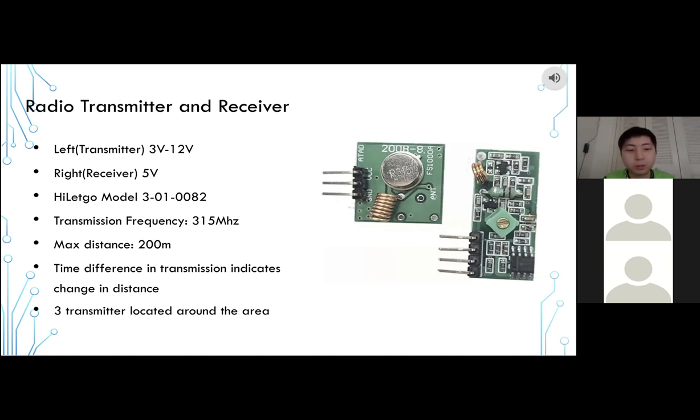By placing 3 transmitters around the pool, constantly sending signals to the receiver, and configuring the time it takes to receive a signal on the boat from the base station when it is at rest, we have a baseline. Once the boat starts moving, the change in the time it takes to transmit those signals would be accounted for as the difference in the distance it moved, triangulating a new coordinate for the boat, working as a local GPS.